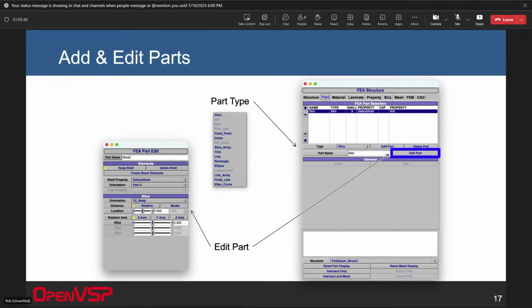And so if you wanted to put something in where you only had the beam elements, so you only had those stiffeners but not the rib, you would choose to delete those shell elements but create the beam elements. That's why you have these three options. You can either keep or delete the shell, and then you can choose to create or not create the beam elements. Depending on whether you have shell and cap and beam elements, you choose the properties to apply for it up here. And then below that are all the parameters that exist for each different part type.